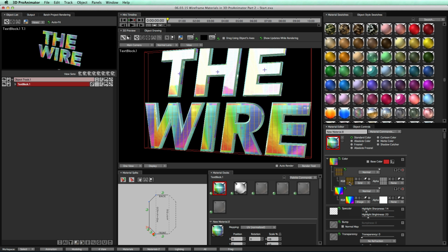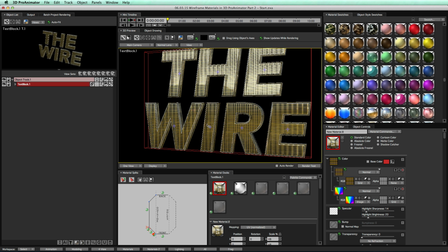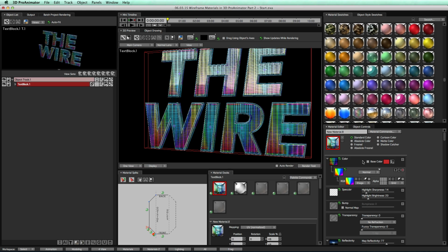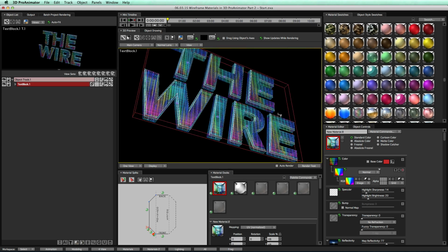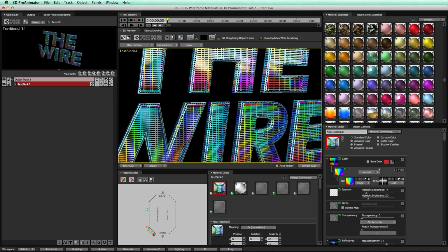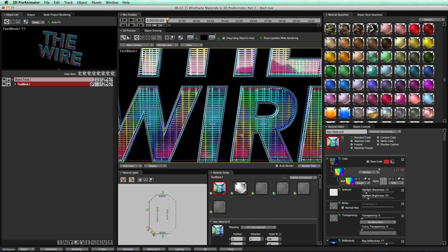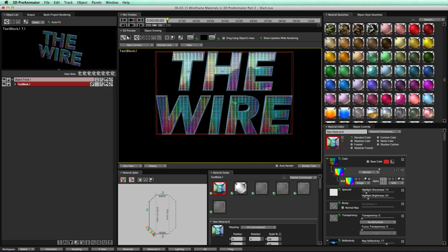So all I have to do is select this RGB channel right here, hold and press Command C on a Mac or Control C on a PC, and then come over to our alpha channel and do Command V on a Mac or Control V on a PC, and boom, then I delete my gold, and now we get this cool, awesome reflection with our rainbow material put on our object. Remember, you can put any picture you want on this word. I just happen to use this rainbow picture because it looks pretty dang cool.